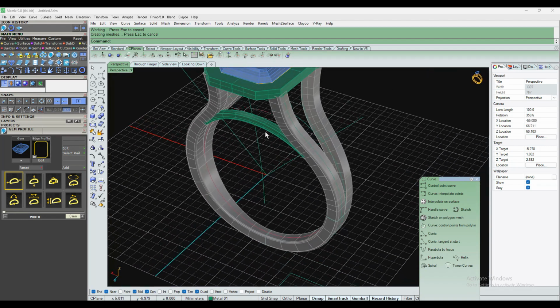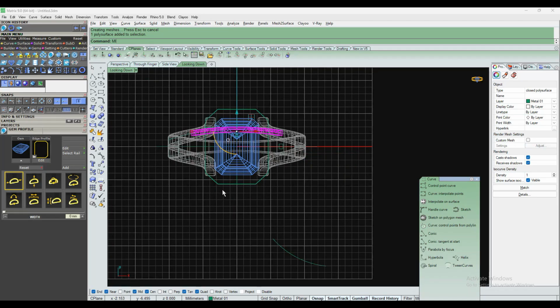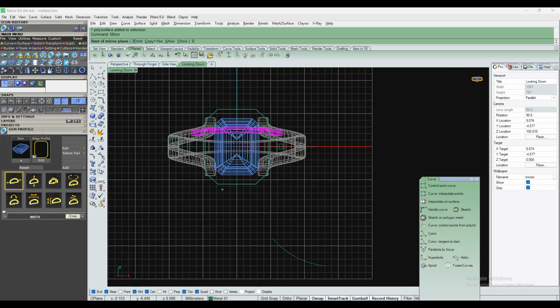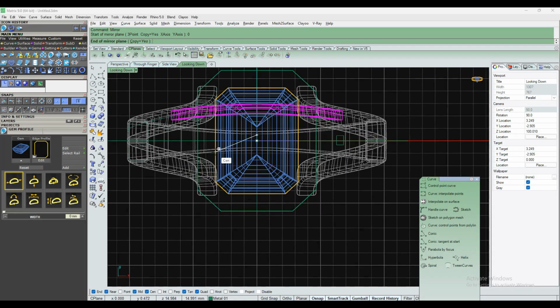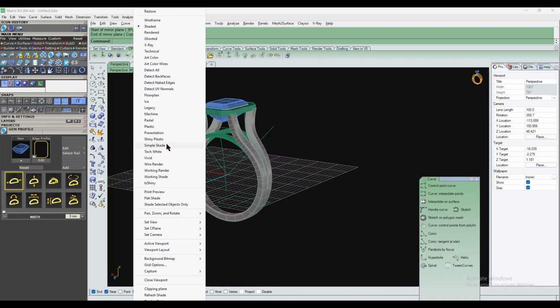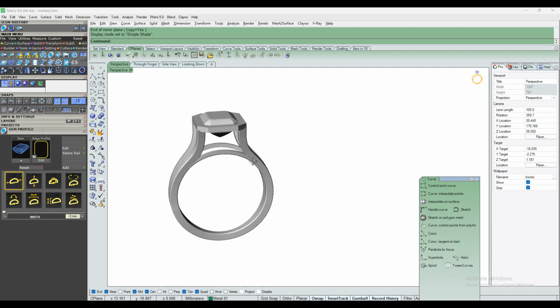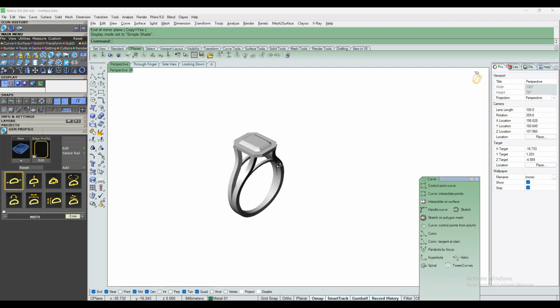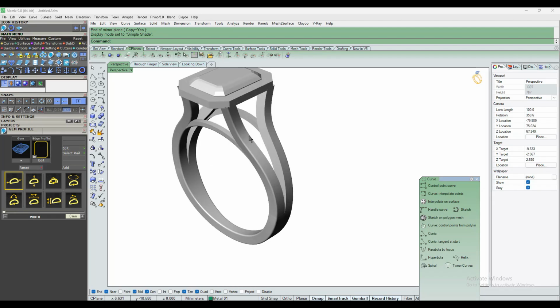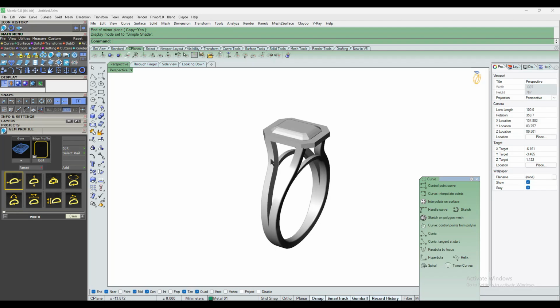And if you want the perfect view, let's first mirror. Type in the mirror command in top view, 0, enter and create one line. Okay, this side. So this is the ring. You can also change your cross sections of this bridge. You can also change your cross sections according to the diamonds. Now in the next session we are applying the diamonds over here and on this shank. Okay, thank you.